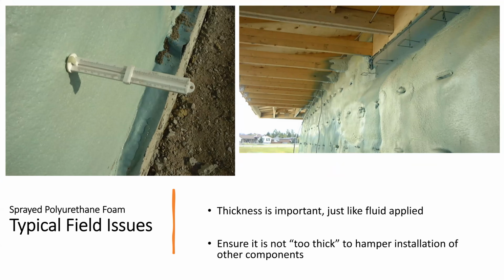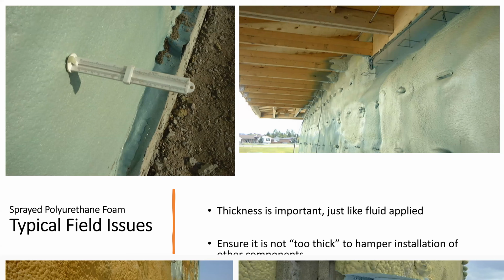And thickness, again, is probably one of the biggest things. These are sprayed at 1, 2, 3, 4 inches, whatever thickness. So we have to go out there and do thickness testing on the final product. We're not doing wet-film testing; we're doing, in essence, testing after the foam has cured. Typically going thicker isn't an issue; you've just given away some free material. But if it's too thick, that might have an impact if a certain gap or airspace is needed behind the cladding for some specific reason. If that's the case, there might have to be a little bit of shaving down of the material.